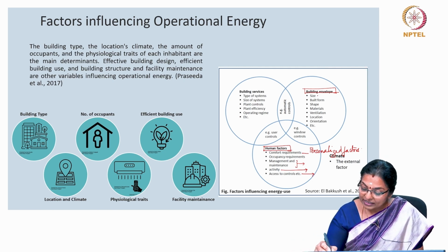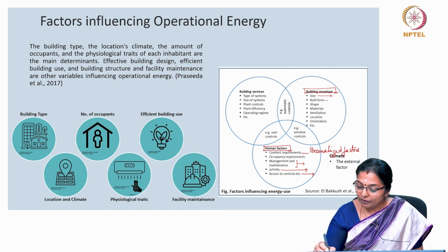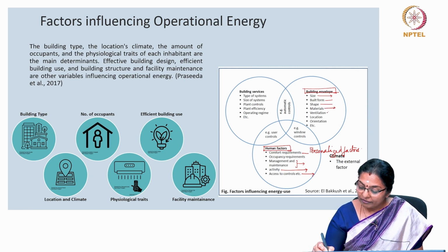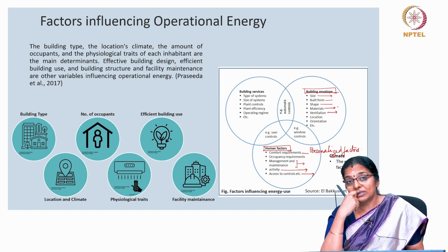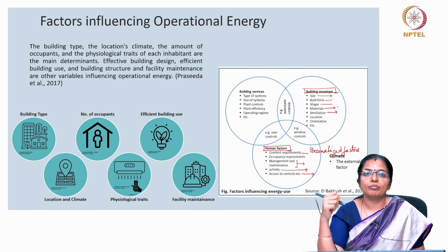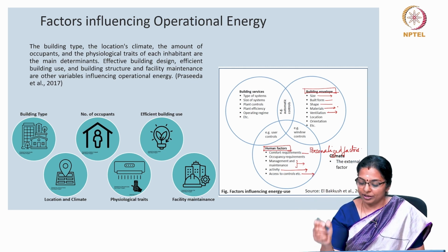So, the size of the building matters, the built form matters, the shape of the building matters, building material used, the ventilation. Building material used contributes in two ways. One is how much heat it is allowing to come inside, and what is the energy required even in the manufacture of that material, which is the embodied energy.